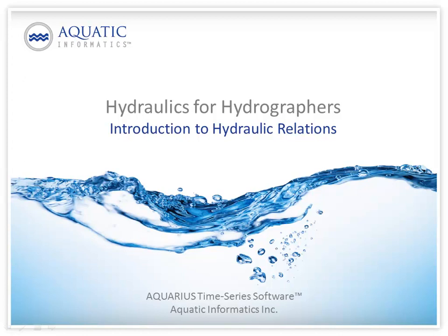In this introduction to hydraulic relations, we will be revisiting some of the material that has already been covered in basic hydrodynamics and in rating curve development, a hydraulics-based approach. What we are adding here in this lesson is a little bit more examination of the underlying theory and looking at deriving the rating curve a little bit differently, and this may help with developing an understanding and the solutions for some of the more tricky problems that come up with rating curve development.